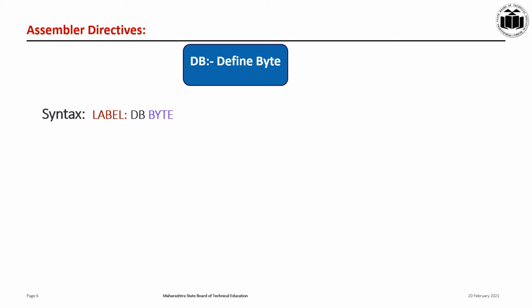While writing the assembly language program, one should not use a reserved word or mnemonic as a label. For example, ADD is the mnemonic for the instruction set of 8051. So, ADD cannot be used as a label. Similarly, ORG and END cannot be used as labels.